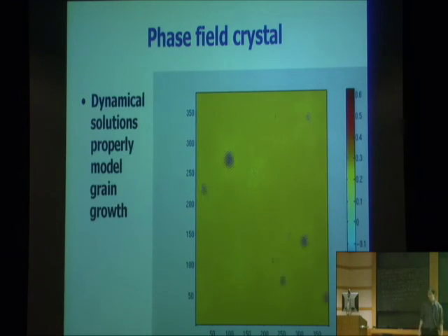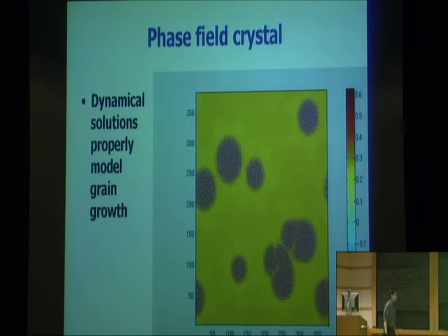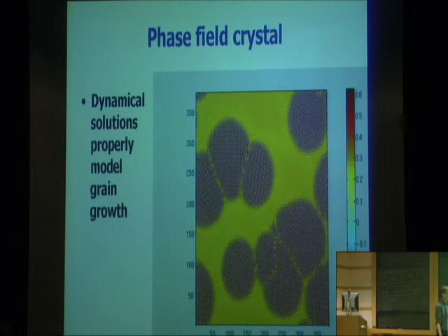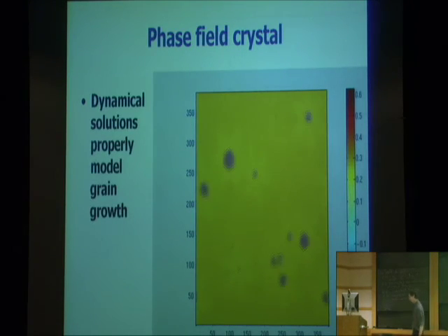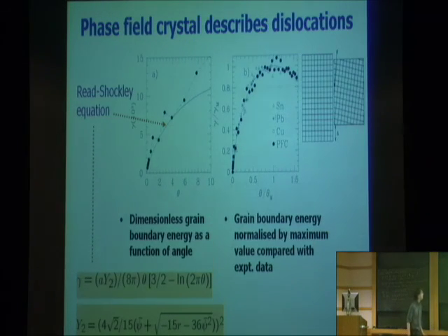These grain boundaries are arrays of topological defects, dislocations, which are strung together at those boundaries. And so this is something that is very hard to do in a normal simulation, simulating polycrystalline materials, but it's quite easy in this particular method.